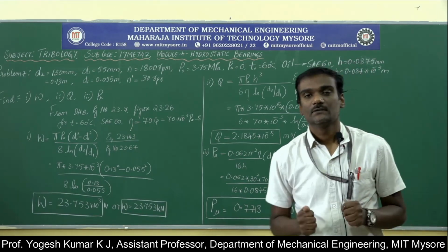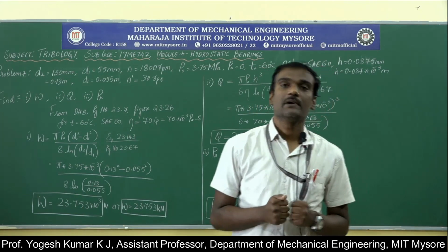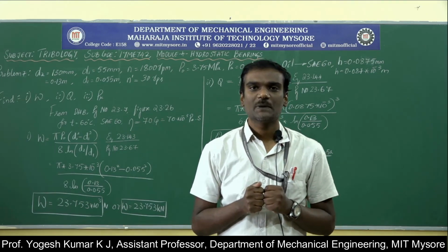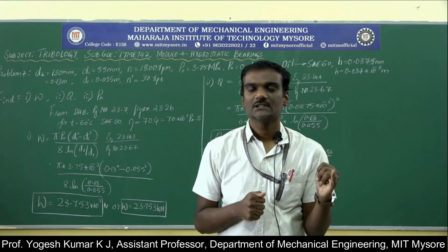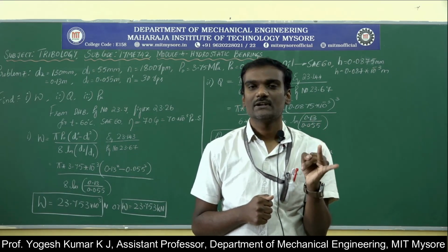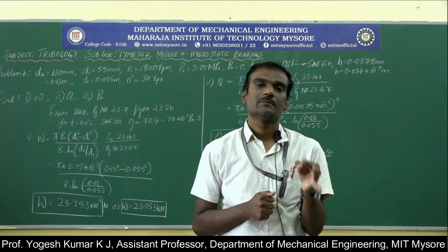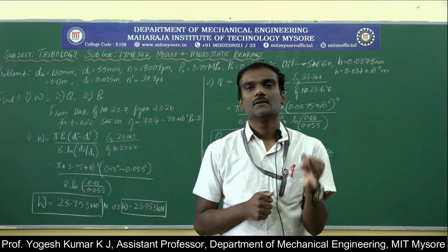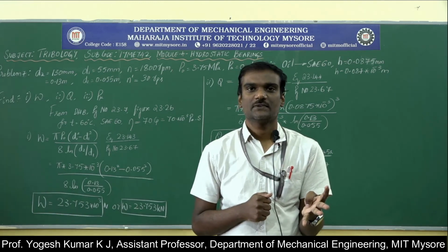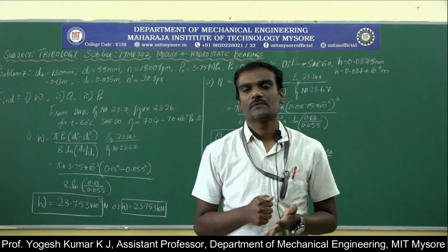So by this we have done around 6 to 8 problems on hydrostatic bearings. The major important things in this particular module are the load carrying capacity and oil flow rate, the two important derivations that we have in this module. The next is the problems based on the load carrying capacity, supply pressure, oil flow rate, power loss due to viscous friction. And one more thing you might be asked is to find out the coefficient of friction.